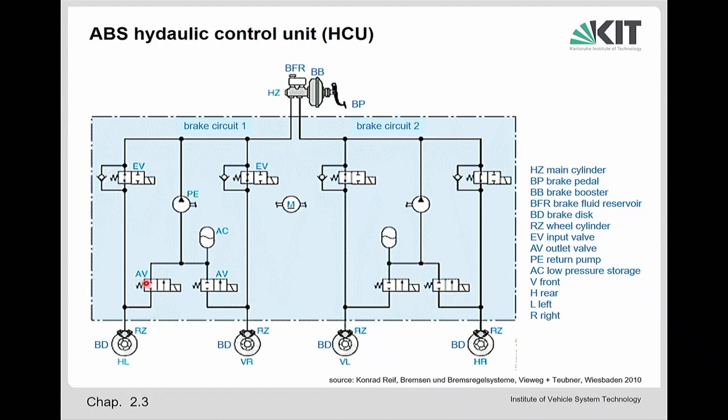And after the braking, the brake fluid, which was flowing from the main brake cylinder in this direction and then going back here, is stored in that reservoir here. So there's just some air in, so this can be compressed, and so the brake fluid can go in here. And after the braking maneuver is finished, the brake is released, so we will not have any high pressure in the main brake cylinder, just an environmental pressure. So then this pump will bring the fluid from this reservoir back to the main reservoir here.